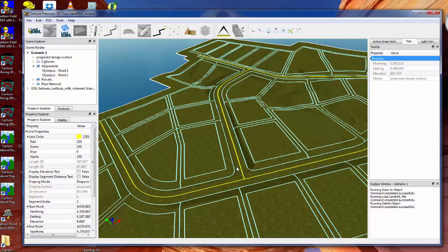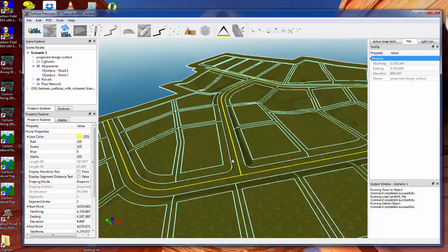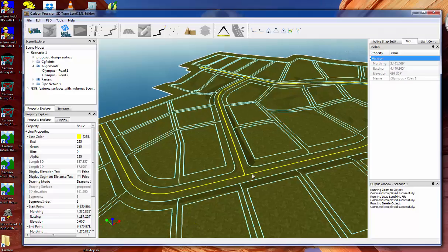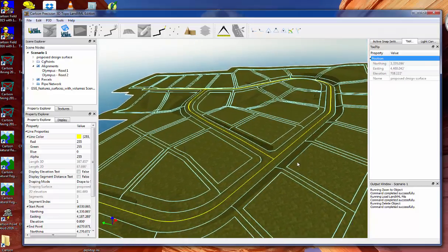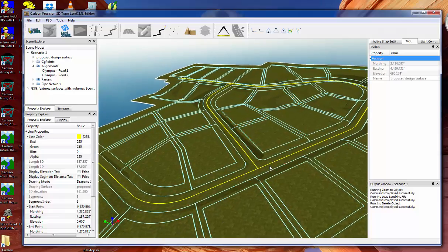We will work with surfaces that just have source data, and we'll go ahead and recreate that. If you have the TIN already defined with the points and faces, we will honor that triangulation and bring it in just the way that the creating application exported it. So obviously this LandXML file no longer looks like a plain LandXML file. It actually has a texture that's a single texture that's been applied to the surface. But single textures are not really nearly as interesting as multiple textures.